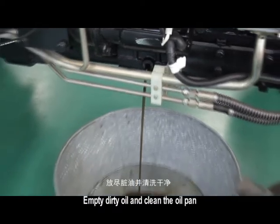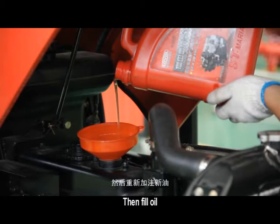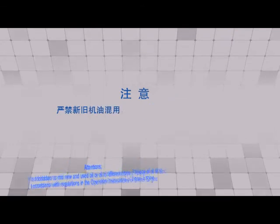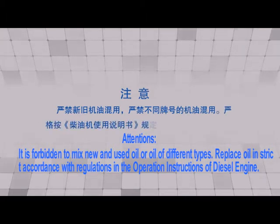Empty dirty oil and clean the oil pan. Then fill oil. Attention! It is forbidden to mix new and used engine oil or engine oil of different types. Replace engine oil in strict accordance with regulations in the operation instructions of diesel engine.